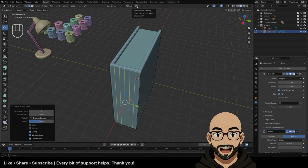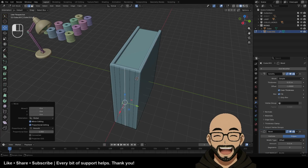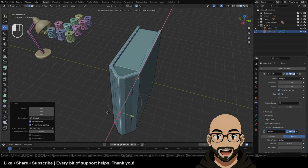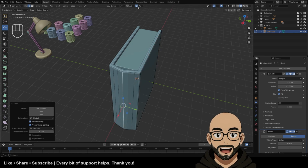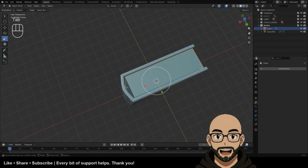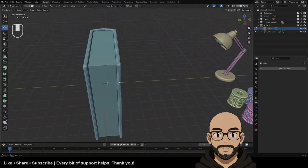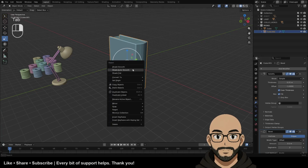And if we turn on proportional editing, select this middle one. As I drag, if I scroll the mouse wheel, I can choose how much I expand and how much I fit that curve, or the rest of the edges on the proportional editing. I'll turn that off now. And then I can just pull this face in a little bit. There we go. We have a book. It's not the best book, but it's a book. Shade auto smooth.